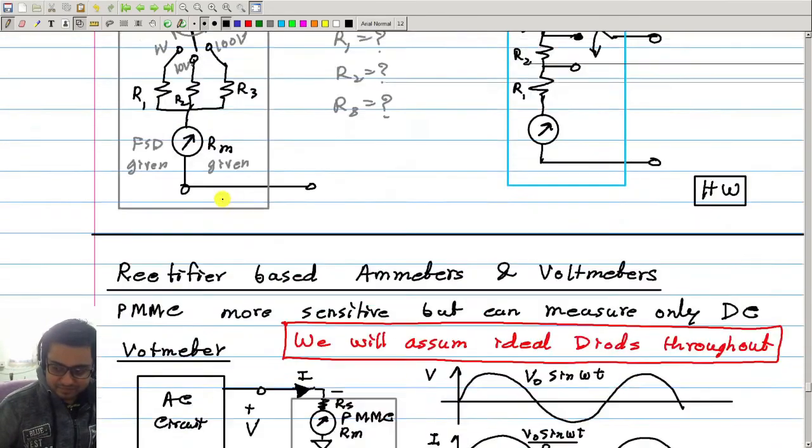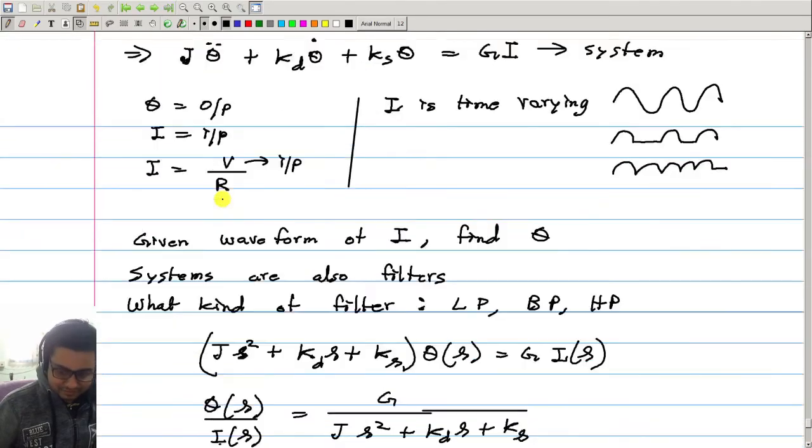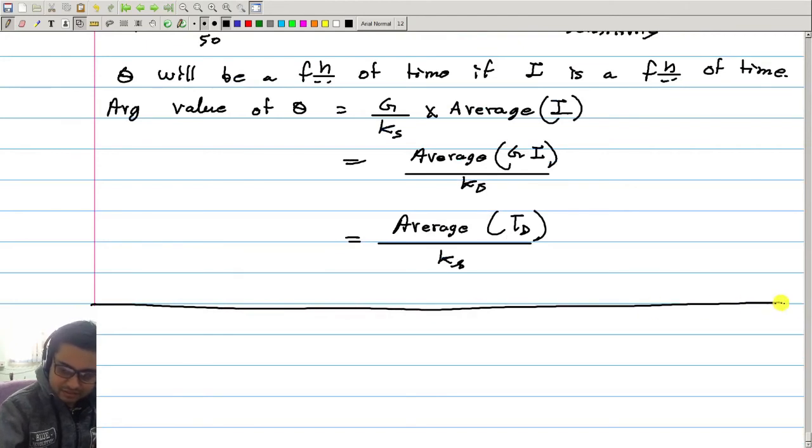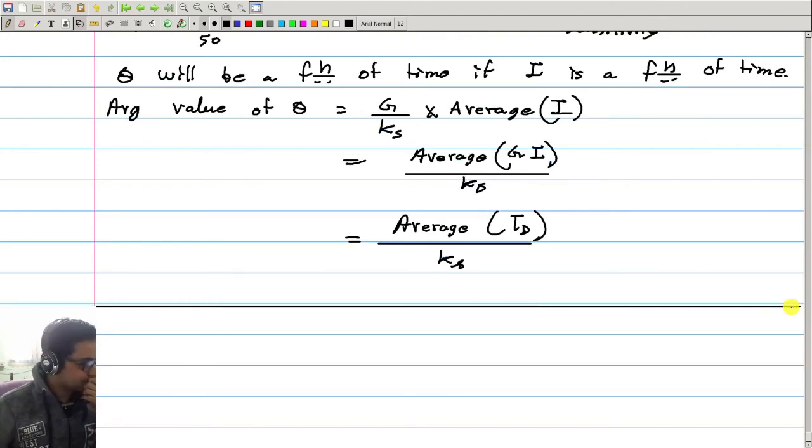You have said here that the KCL is violated in the case of that inductor and ammeter. But we apply KCL when the circuit is complete, when the switch is closed. So we apply KCL at time greater than 0. At that time u of t is 1, so I think it should be I only. Also, I thought later about it. So you are absolutely right.